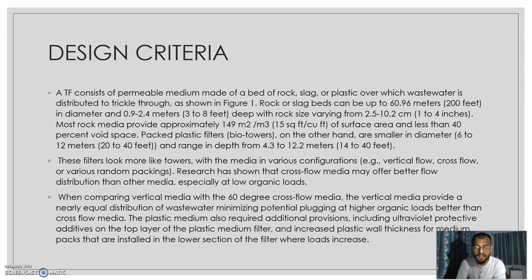The plastic medium also requires additional provisions, including ultraviolet protection, additive on the top layer of the plastic medium filter, and increased plastic wall thickness for medium packs that are installed in the lower section of the filter where loads increase.